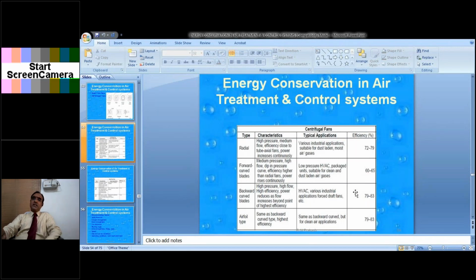We have to ensure that the air is clean and there is no fluff or dust coming on that, because the gap between the impeller and the scroll and other things will be less. So all these parameters we have to see in detail before selection. As I said earlier, the propeller fan efficiency is about 45 to 50%. Many places the propeller fan will be working. Some places even this cooling tower fan they will be using for some exhaust, just for the namesake running without knowing the pressure and volume and other things.